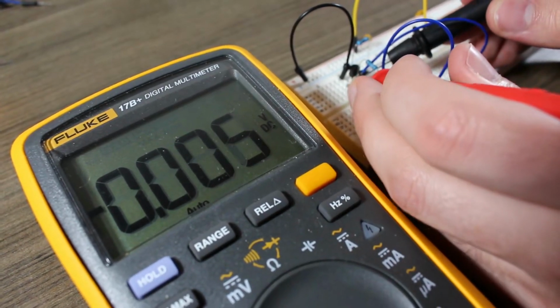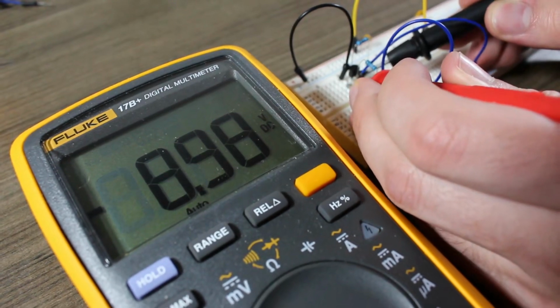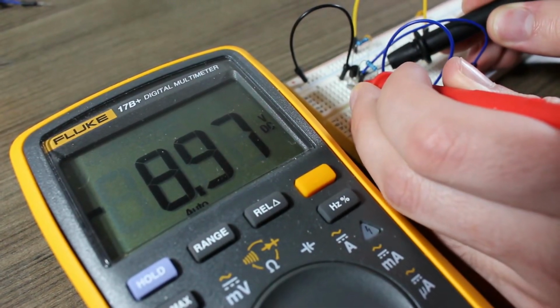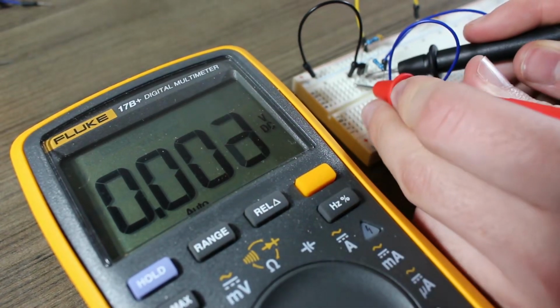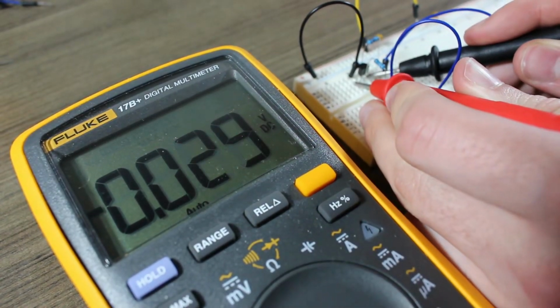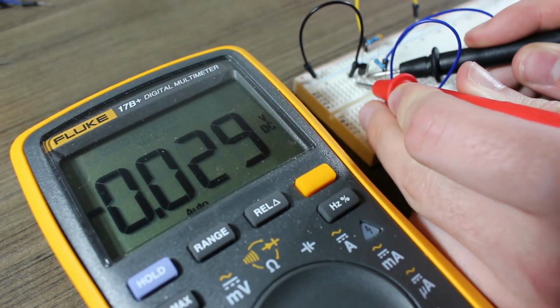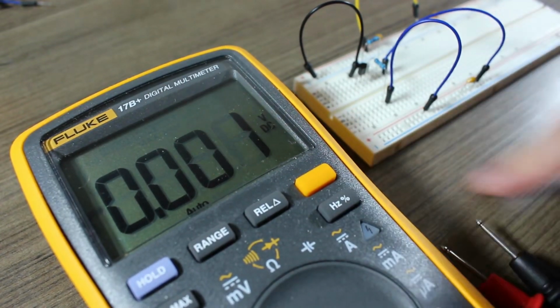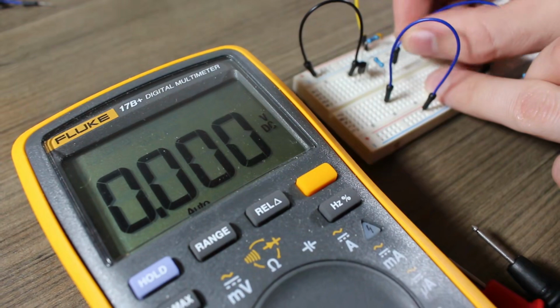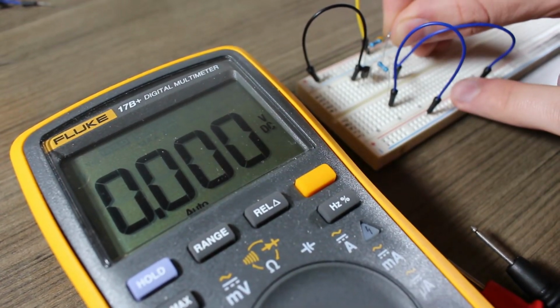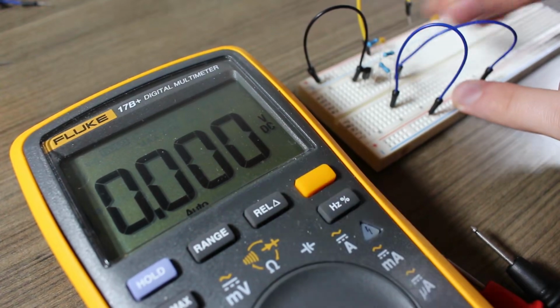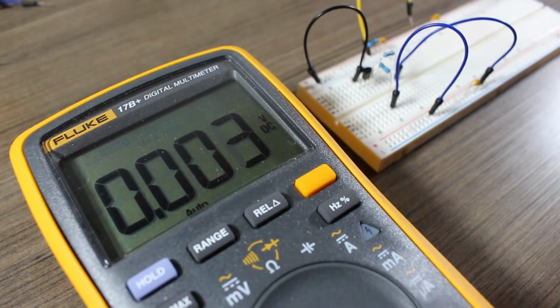Saturation can be shown at the end of that experiment though, with the 100K collector resistor. The base current was trying to keep the current constant through the transistor, but the resistor simply was way too much for the power supply to get over to maintain that current. In other words, saturation occurs whenever the transistor is trying to deliver that constant current, but the impedance is just too high for it to reach. In other words, saturation means that the transistor is fully on.